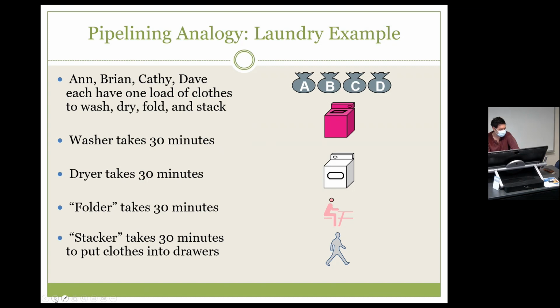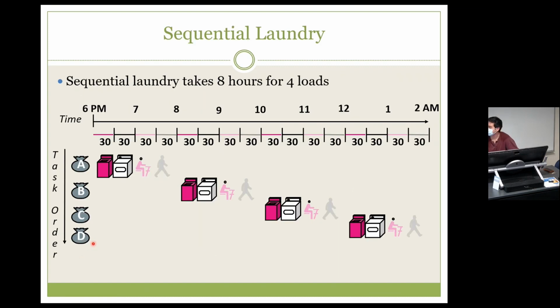So if we do this analogy for our single cycle design, what we're doing is we're first washing, then we're drying, folding, and putting it away, and then we start the next batch of laundry. Right? So it's like fetching the instruction, reading the registers, maybe accessing memory, and then writing back the results, right? And then we do the next step.